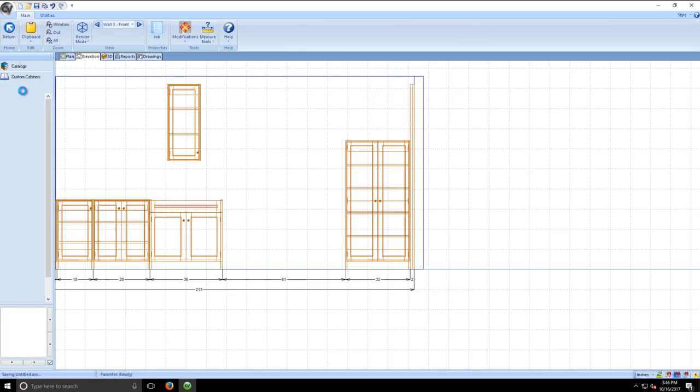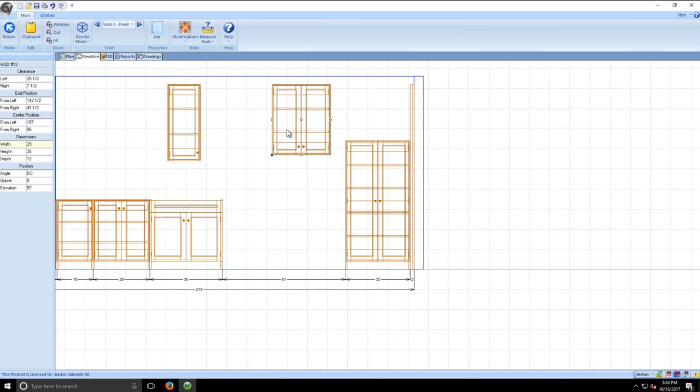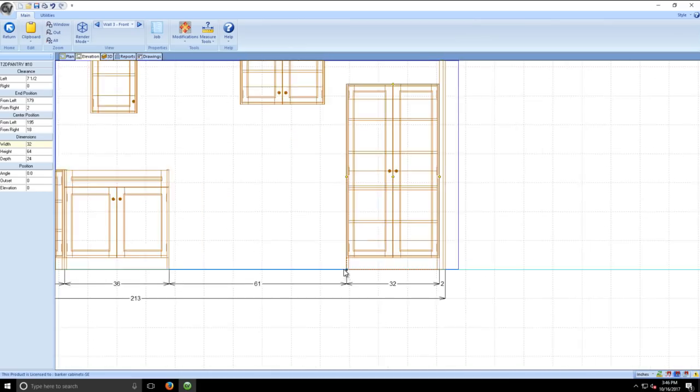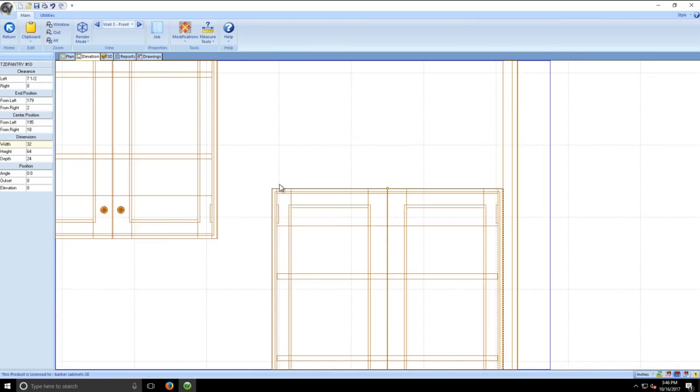Unless you were just getting started in it, which is probably a reason you wouldn't want to order cabinets from that company. So what we do, 2 of them. You take this one, you order a tall 2-door pantry, and then you order a 2-door wall cabinet, and you stack it on top. Okay? That's 64 inches tall, and that's a proper pantry lower portion. Highly recommend 64 because that includes the toe kick all the way up to the top of the cabinet. That's the height you'd enter it at. And that's our default for our tall pantry cabinets.